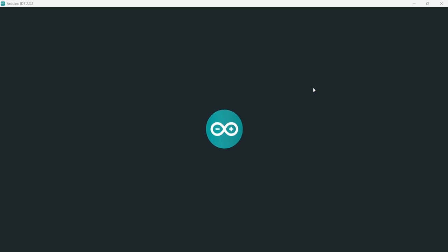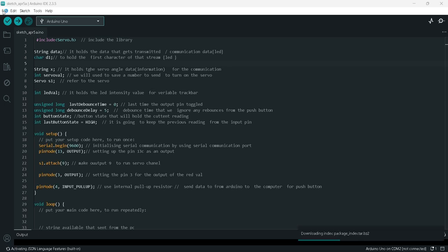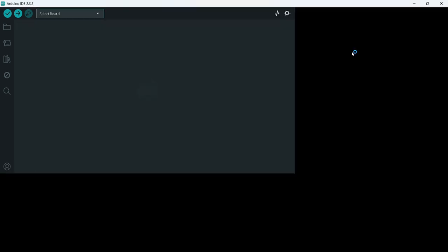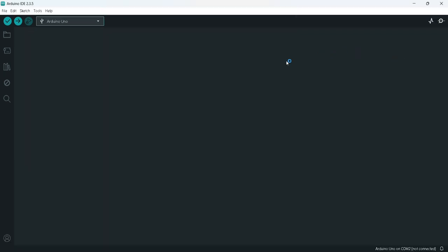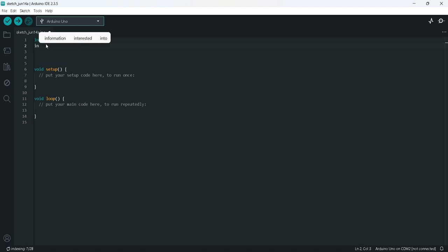So let's open the Arduino IDE. Next, create a new sketch. Let's expand this. So let's bring this down first. Okay. So first we'll take some integers so that we will define the pins. Let's define the pins. Let's set LED pin 1 equal to 7, in our LED. Okay. Let's try another one. Let's take 8.